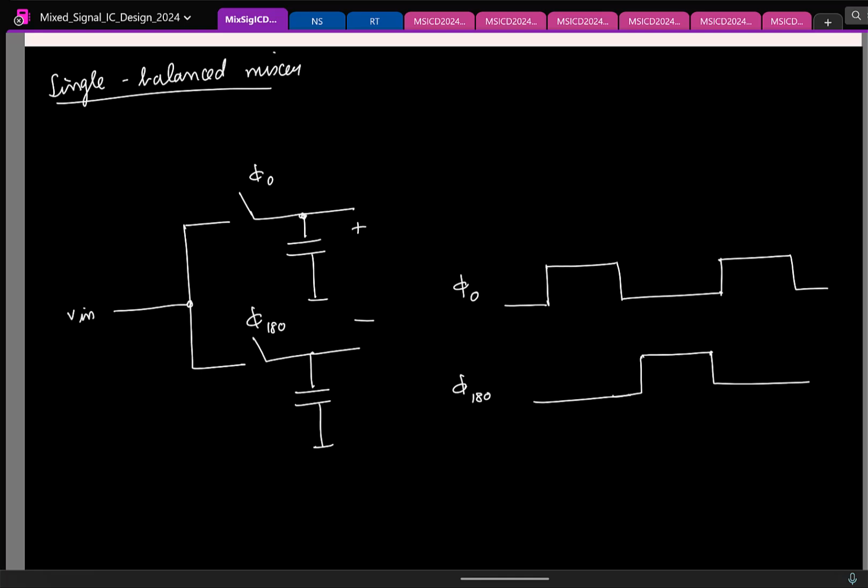So here we are having a circuit where there are two parts. Each of the parts is tracking the input for 1/2 of the clock period. But it turns out you don't have to stop with two parts. In general, you can have n of these in parallel, and make sure each of these n branches tracks the input for 1/n of the clock period. So let us say from 0 to Ts by n, the first branch tracks. From Ts by n to 2 times Ts by n, the second branch tracks, and so on. This also you can do, and the motivation to do this is the following.